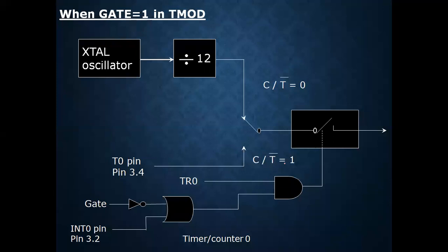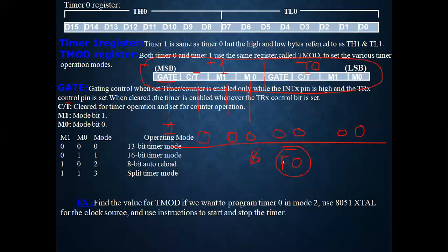This figure depicts how the timer operation is occurring, and especially this diagram denotes what happens when the gate pin is high in the TMOD register.